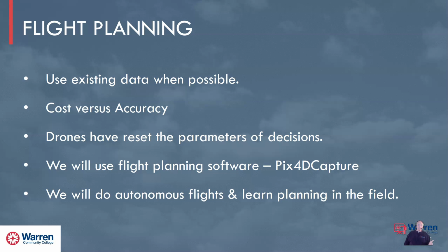Drones have really, and realize this, reset the parameters on these decisions. And as the pilot, this is where the skill set is. What ground sampling distance do I need to get my client? What end result do they need? What level of post-processing work do I need to do to get them the level of accuracy that this project requires? All that takes skill, takes knowledge, and that's what we're doing. That's what this course is about.